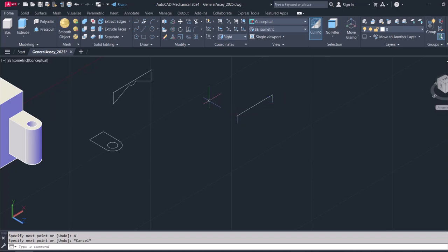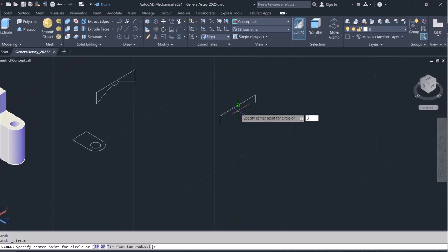So I'd go for circle, and that circle has a radius of 2, so center radius, so midway, and then down by 3, and the radius should be 2, and then I can offset the 22 line by a distance of 2.